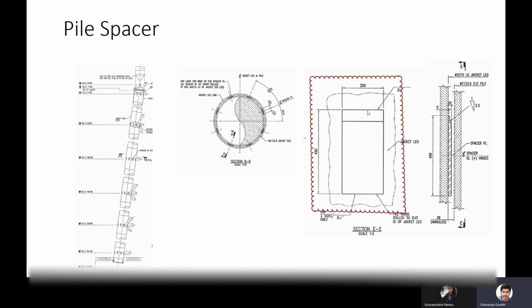Why? Because this weld is not going to take part in any of the calculation here. The entire shear, the entire length and this length, is going to take part. For that reason 8 is given at the perimeter of this one, not on the top. Only 5 is given on the top.